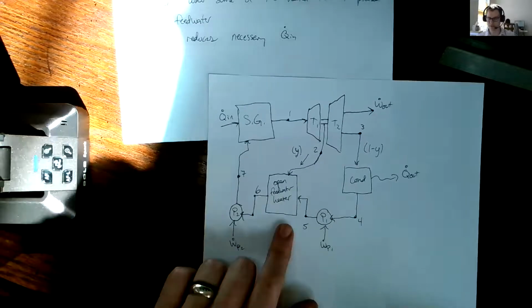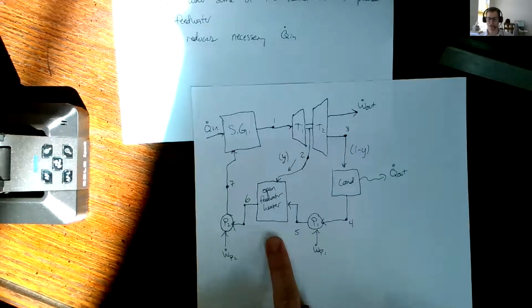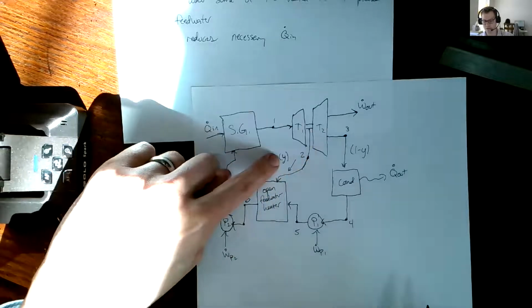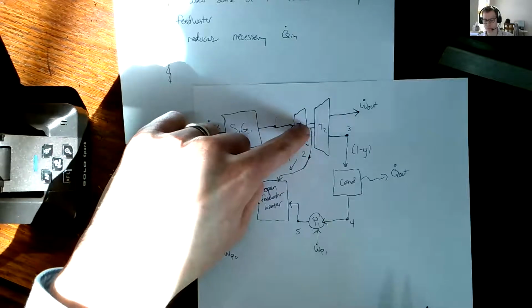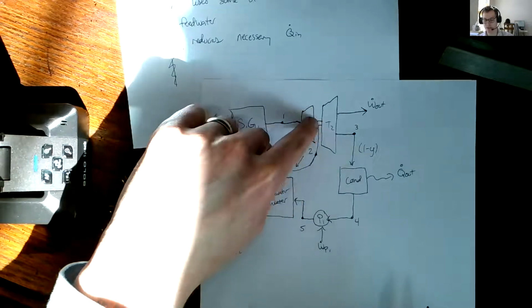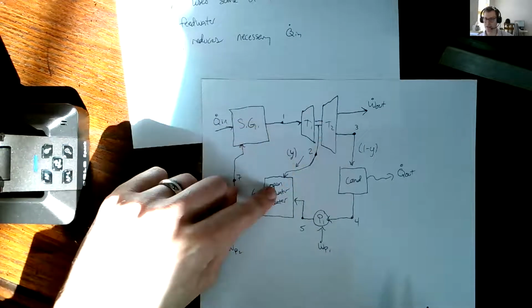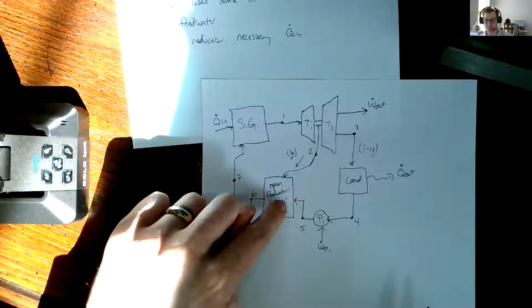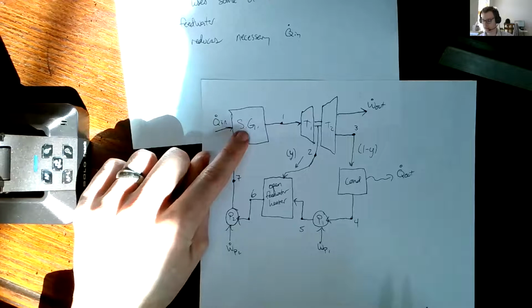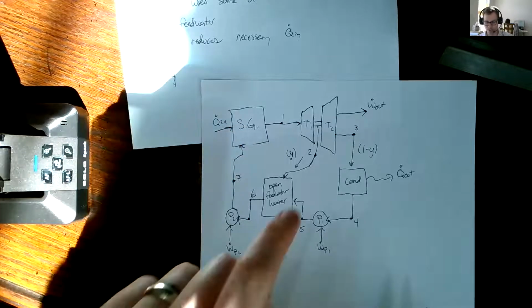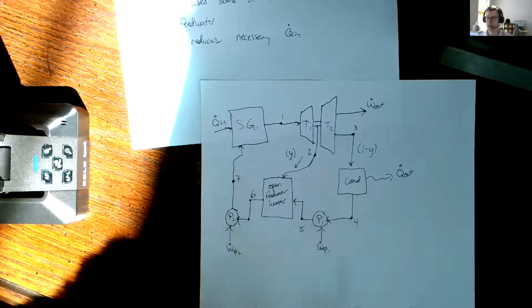So that's what this system is going to look like. We're going to divert some fraction Y away from the second turbine. So it all goes through the first turbine, but only part of it goes through the second turbine. And the part that doesn't go through, we're going to pass into this feed water heater to help us alleviate some of the heat load that we need to put on here. So we'll draw a diagram for this and work an example on Monday.